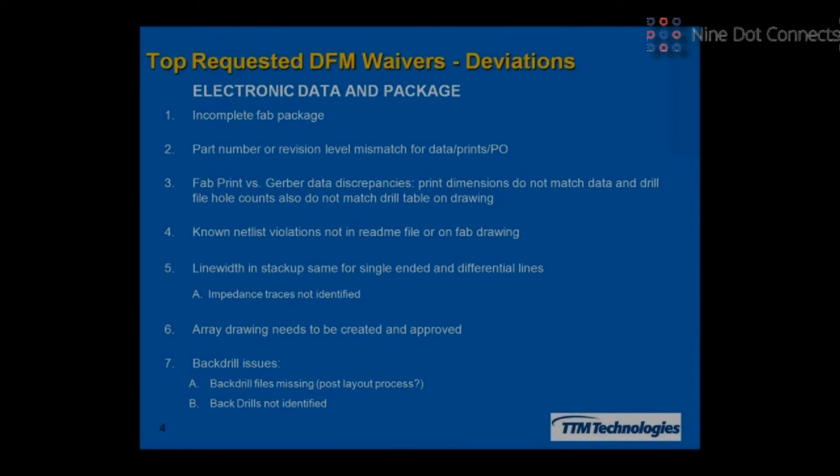Other issues are like non-plated holes hitting copper, solder masks not being specified or being specified incorrectly, or the fabricator has different capabilities. So clarifying all that up front gets to be a little bit of an exciting discussion. Solder mask webs based on capabilities. So some fabricators can do a certain amount of solder mask web between BGA pads. And then also removal of non-functional pads.